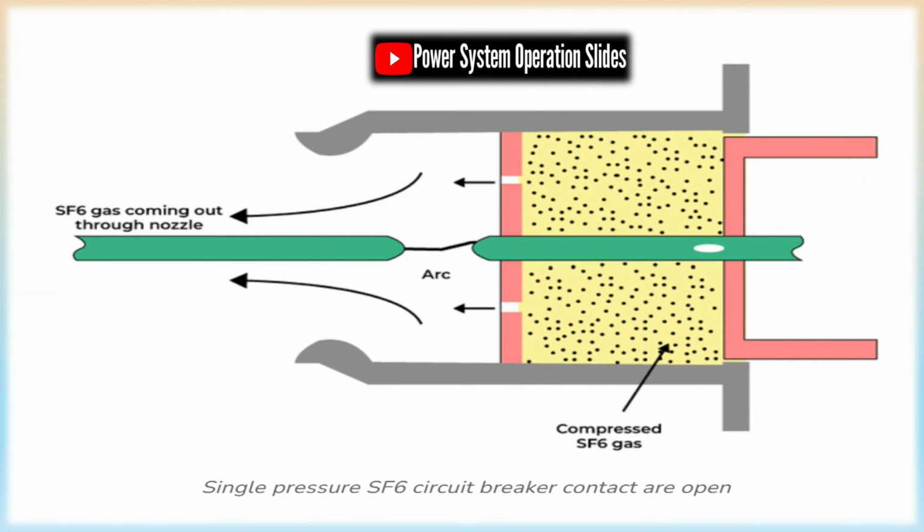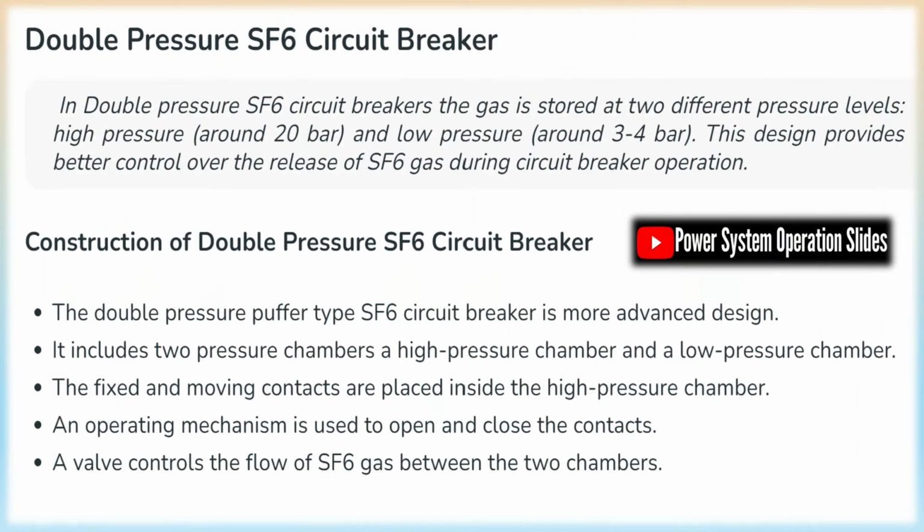in the interrupter unit. It houses two sets of contacts which are commonly called the main or normal current carrying contacts and arcing contacts. Both types of these contact sets have one stationary contact whilst the other contact is able to move. Current carriers providing connection to the external circuit breaker terminals are connected to the stationary and moving main contacts. The tips of all circuit breaker contacts are coated with a copper tungsten arc-resistant material.